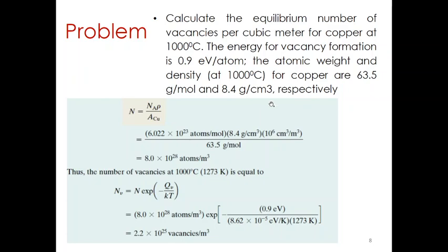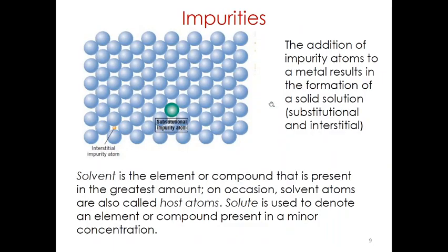Next is impurities. There are foreign atoms in the material. Some impurities are undesirable and must be removed by purification. Silicon used to produce integrated circuits, for instance, can tolerate less than 1 impurity per 10 million silicon atoms. Other foreign atoms are introduced for their beneficial effects. Examples are the doping of semiconductors to make them N-type or P-type conductors. Impurities are also introduced to increase the electrical resistance and the mechanical strength of metals.